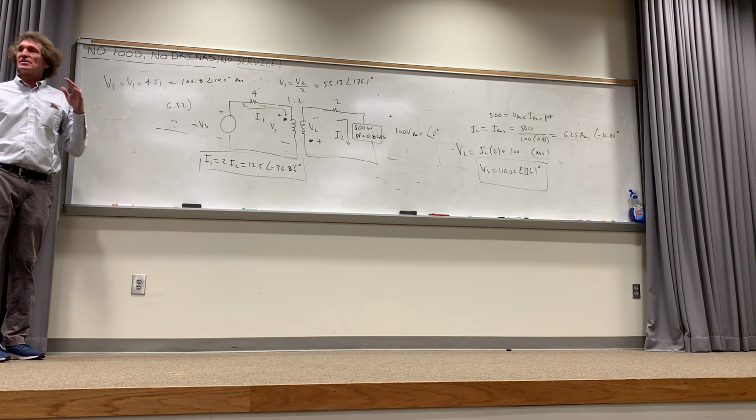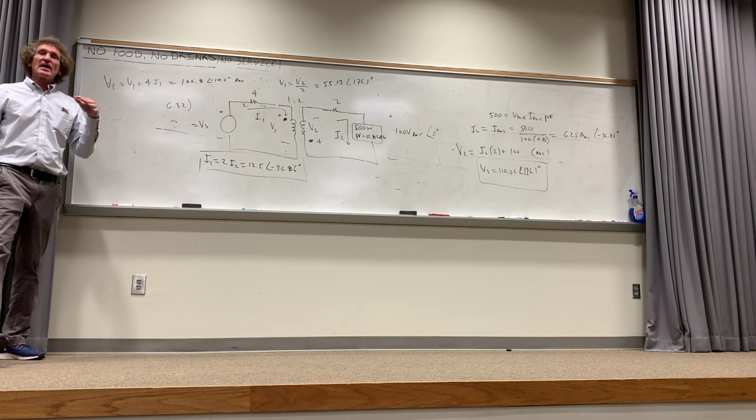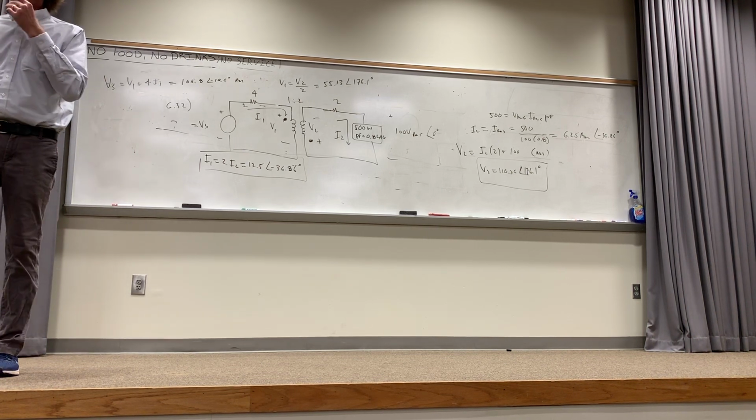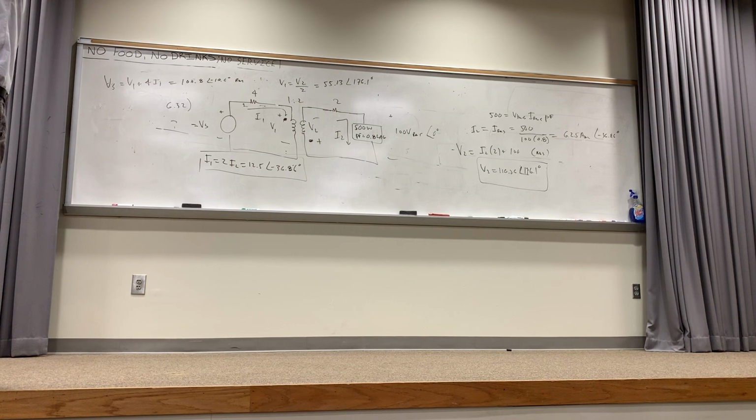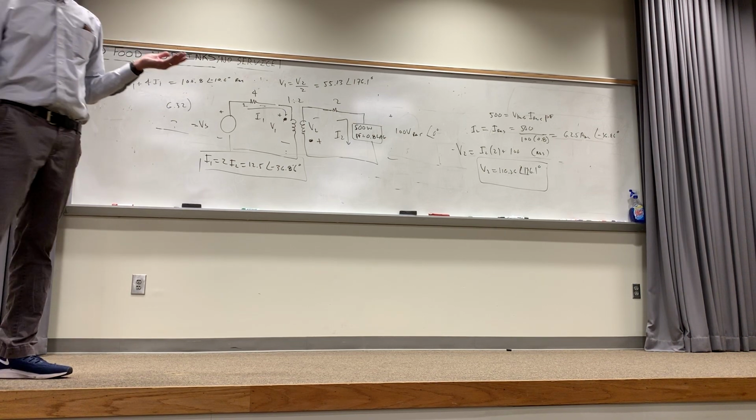The whole idea is the RMS is really the effective voltage. It's lower than the peak value. Peak value is the top of the sinusoid, right? The very peak level possible. So you multiply it by square root of 2, or 1.414. Follow me? So it would be about 141 volts is really what I'm talking about. That's RMS, but they want peak.